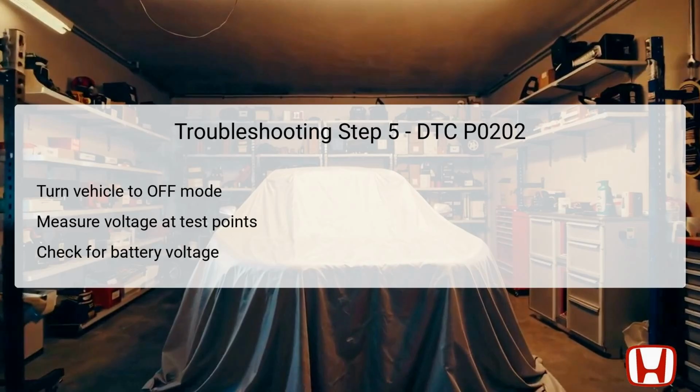If voltage is present, proceed to step 7, as this indicates that the power supply line is functional. However, if no voltage is detected, it requires an inspection and possible repair for an open in the +B engine wire. The goal of this step is to ensure that the entire circuit leading to the injector relay is fully operational before moving on to further diagnostics.